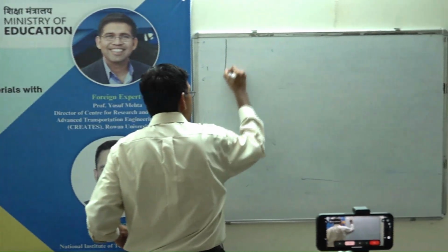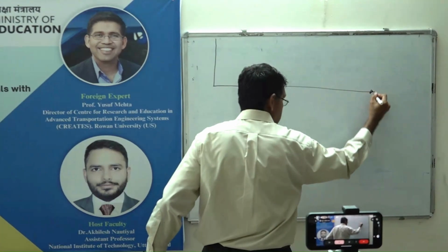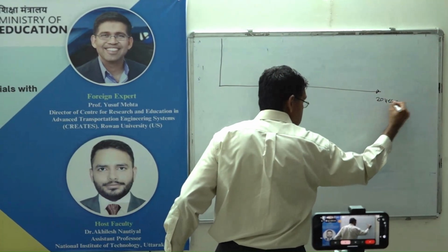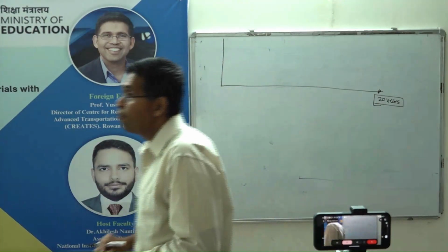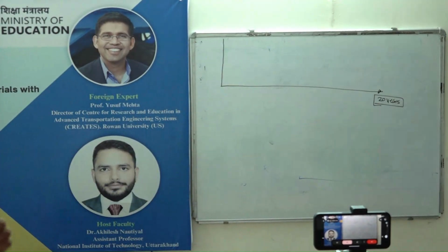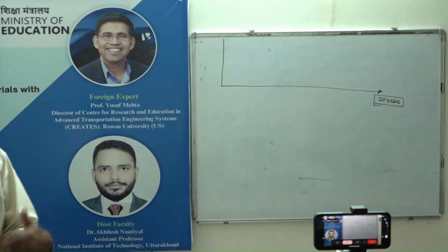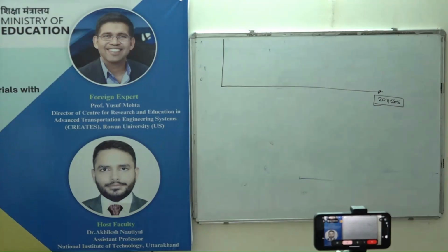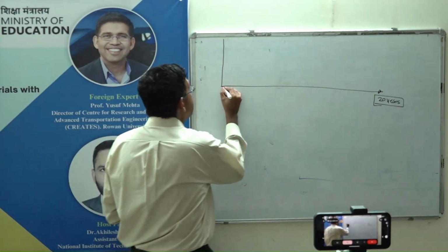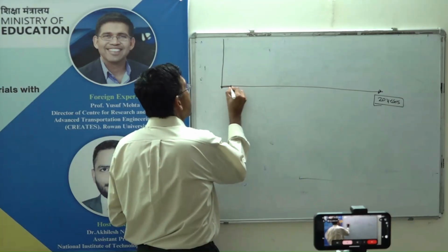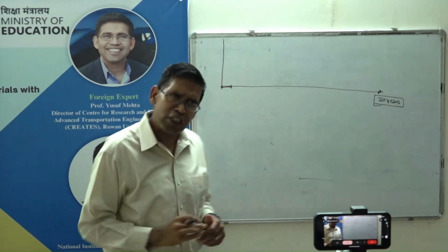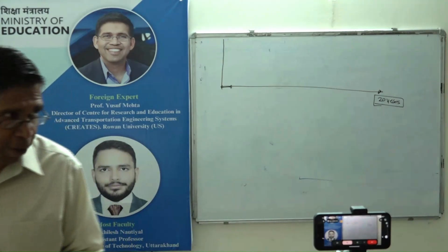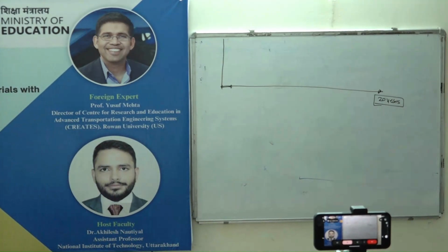So the entire 20 years in the MEPDG is divided into 15-day increments, half a month, right? So you can do the math, right? 24 times 20, 480, correct? So each box is 15 days. Everybody understand that? Okay, now, in that 15 days, there is an assumption made that nothing changes, which is a fair assumption for a 20-year period for pavements, right? We're not developing a nuclear reactor, right?